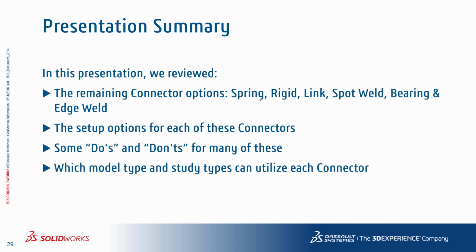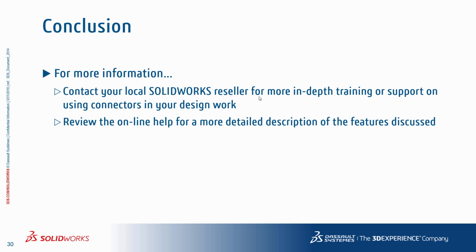In this presentation, we reviewed the remaining connector options such as springs, rigid connector, links, spot weld, bearing connector, and edge weld connector. We looked at some setup options for each one of these connectors, some do's and don'ts, and also finally we looked at what model type and study types can utilize each one of the connectors.